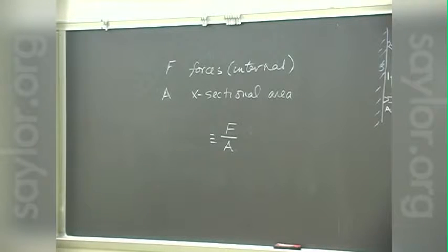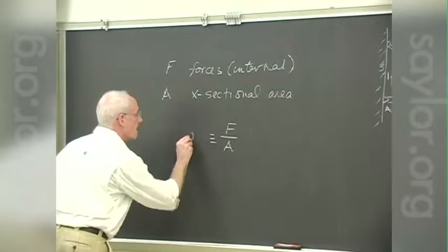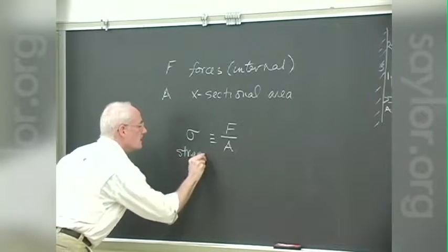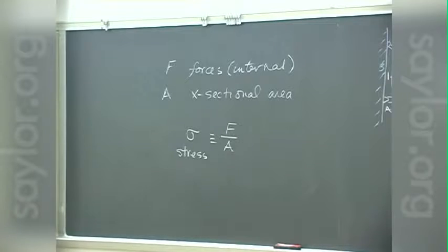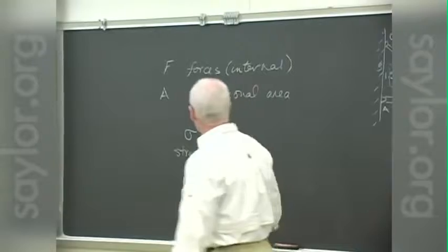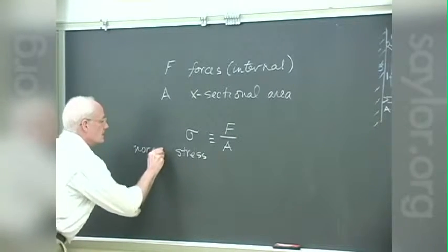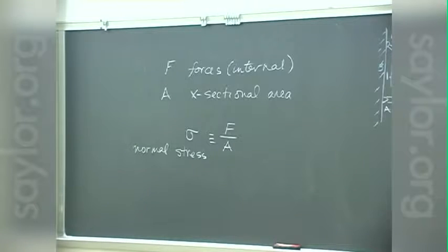through this class, and we call it the stress, and give it the symbol sigma. Greek lowercase sigma. And it's the force in a member divided by the cross-sectional area that is supporting that force. More specifically, this is known as the normal stress.